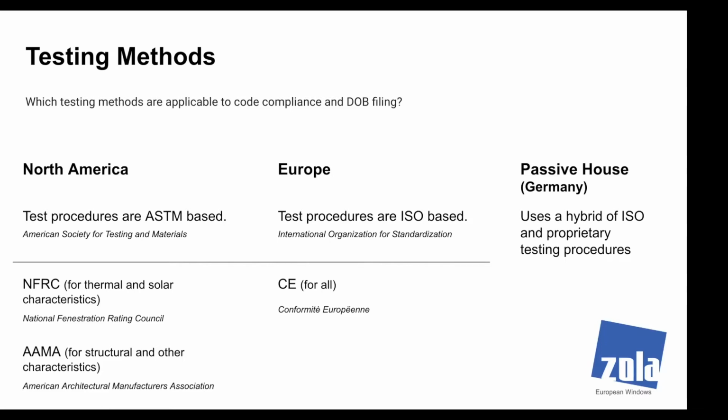One of the key components of this is that in Europe, the ISO testing criteria for windows and doors is really component based. So it's frame, glass, spacer, install, and all of the componentry related to that. Whereas in North America, NFRC and AAMA is predominantly based on in situ testing of actual windows as installed into a test criteria. So they test specific actual real windows.